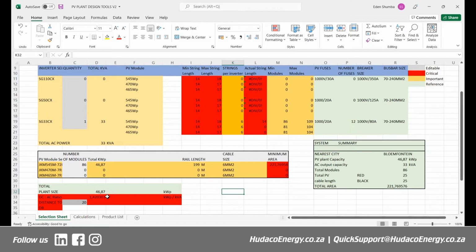Okay, but if we're to say maybe, let's say 80, for example, our DC to AC ratio is still high, 1.3. We want it to be around 1.25. So let's say 75 panels. Yeah, now it's finally round about there.